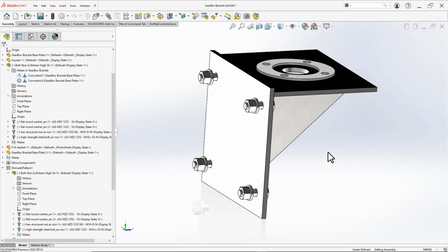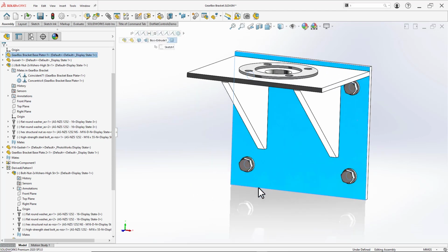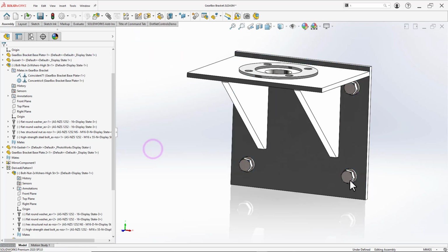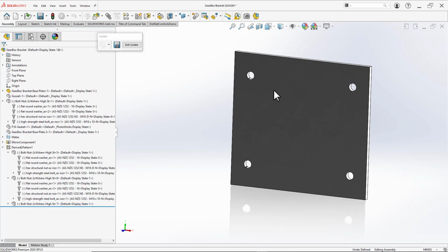Hello, in this video tutorial I want to talk about the linear pattern in SOLIDWORKS. Using linear pattern for a part document gives you the ability to use the same feature, a similar feature, in an assembly environment. For instance, in this case, I've used the linear pattern for this part, and because of that, I can benefit from another pattern in the assembly environment. It has a weird name, but it's called pattern-driven component pattern.